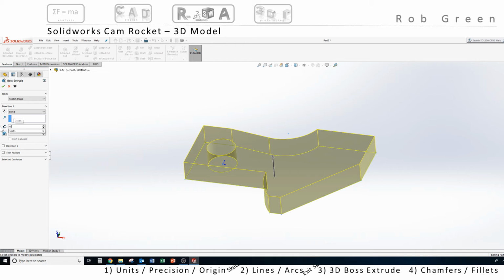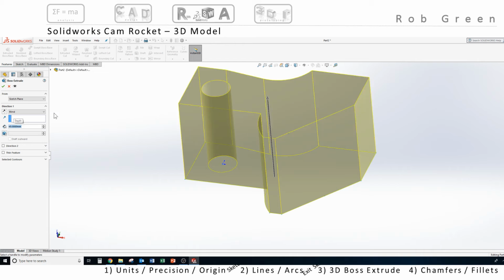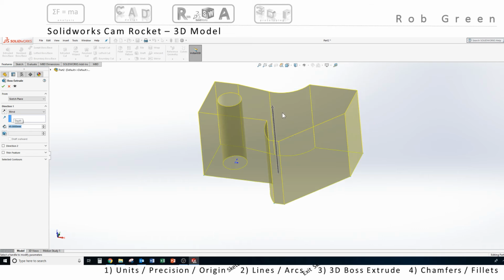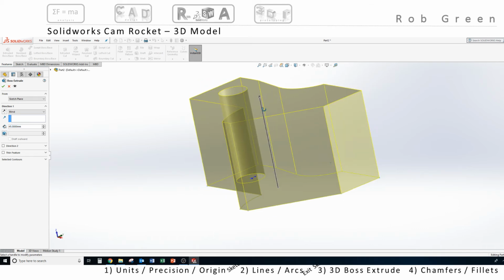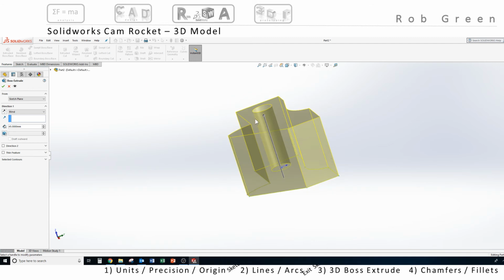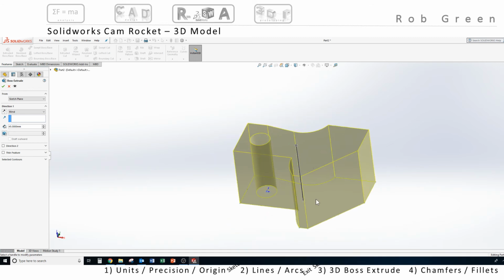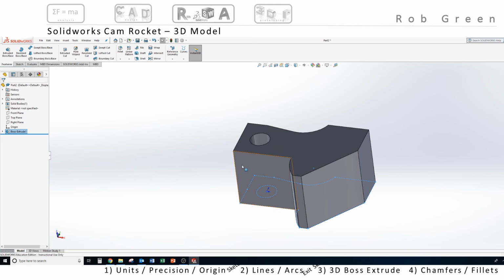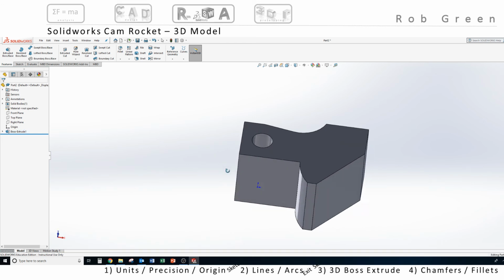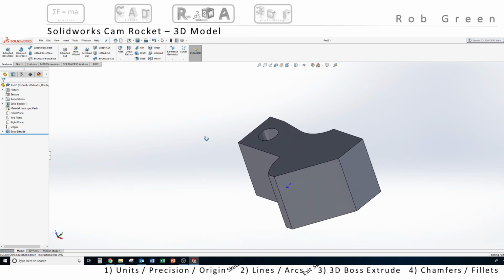When I enter 45 and press enter, my preview updates to that 45 millimeters. I can rotate, I can zoom out and in and look at this part from every direction, decide if that's exactly what I want. If it is, I can click the green check mark. My part turns gray, telling me that that is the finished command.